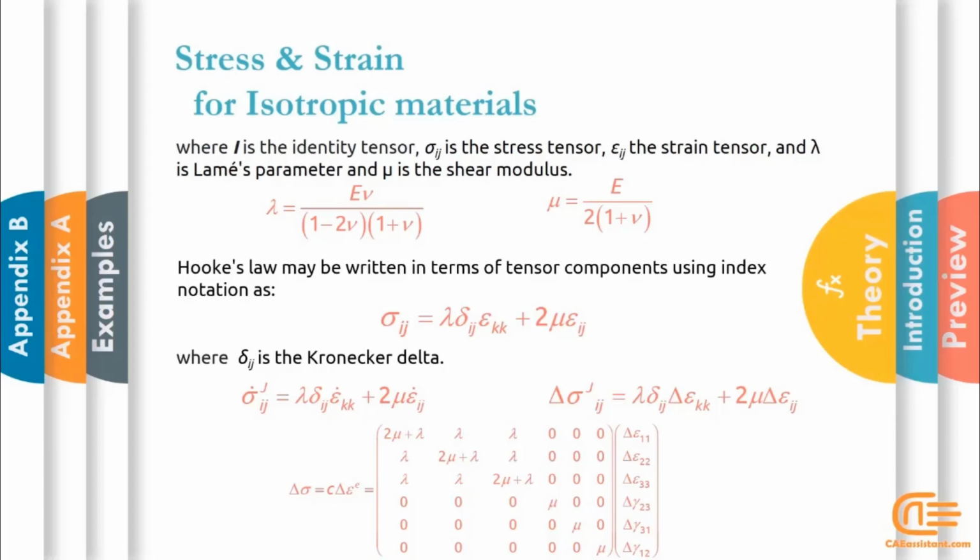It's true that there are relations for the default elastic model in the Abaqus material library, but the process is important here. The main part of your job is to prepare these relations for your material and write them in the subroutine. Of course, this section has nothing to do with subroutine writing and requires more computational theory of elasticity and plasticity. It doesn't matter if your model contains elastic properties or plastic or damage. You need to get these relations for all the properties and get the equations for them.